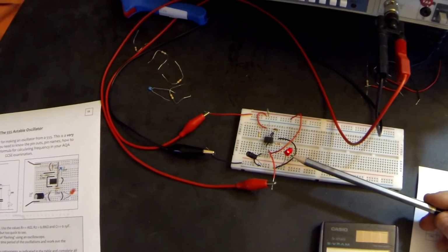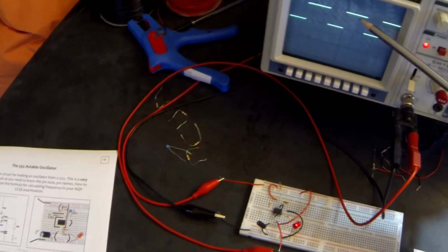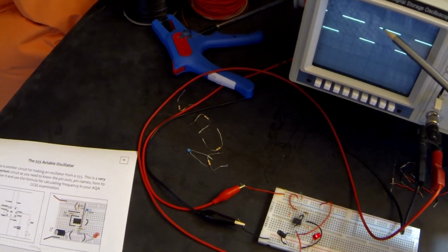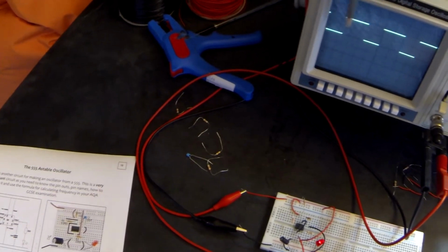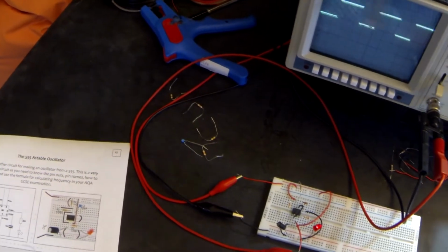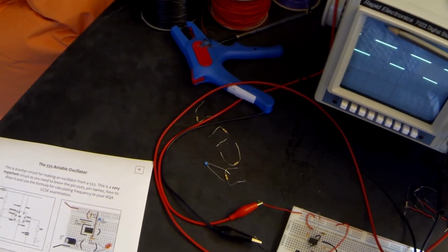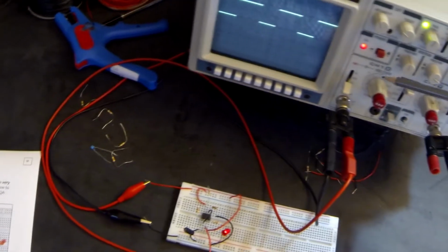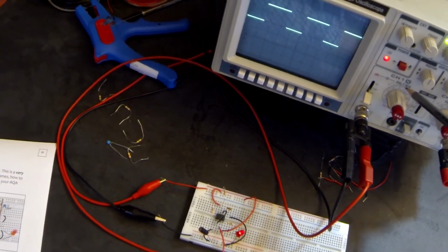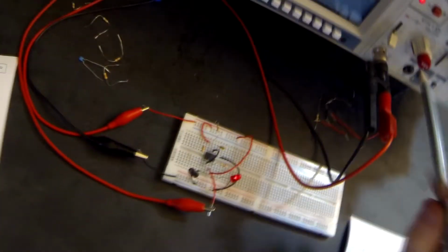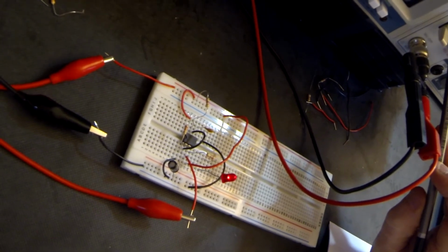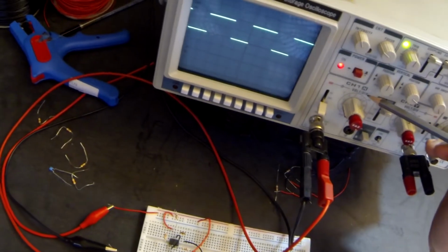Well, if we have a look at our oscilloscope trace, our LED is currently in the circuit, and we can see from this trace the amplitude of the output. Now, we have been working on a horizontal axis looking at the time base, but we can do exactly the same by measuring the number of divisions upwards and then looking at how many volts per division are on our vertical axis. In this case, we can see that the dial is pointing to 2 volts for each division.